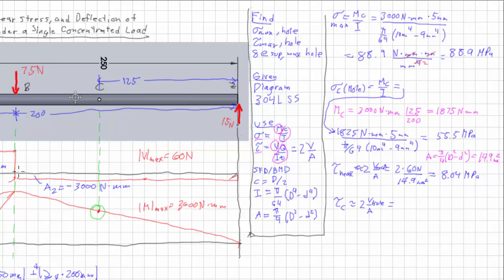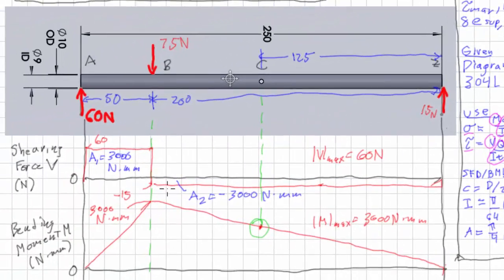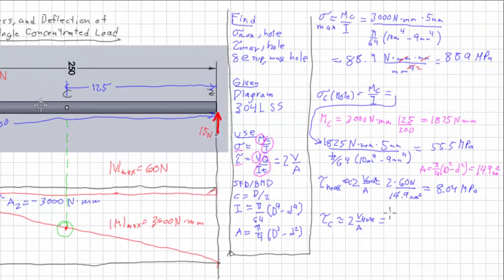And we have to look at it again the same kind of way, that we have to find what the shearing force V is at that point. But this is really easy because it is a flat line all the way across. So whatever it is over here, and in between, it's 15. Don't have to worry about the negative because we can use the absolute value.